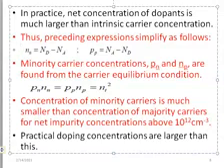So in each case, the concentration of the minority charge carriers is much less than the majority charge carriers, either it is N-type or P-type. And the impurity that satisfies this condition is that the net impurity concentration, that is the difference between Na minus Nd or Nd minus Na, we expect the difference to be above 10 raised to power 12 per centimeter cube.